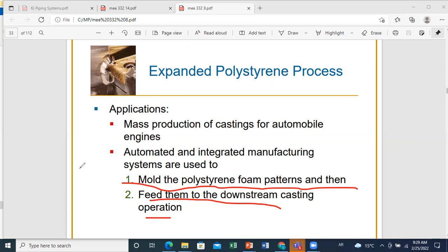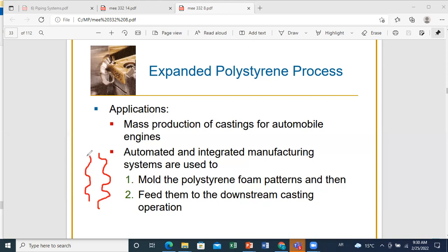In general, this system presents the advantage that you don't have to separate it into two parts, so you can directly create the whole system without having to divide your mold into two parts. Plus, you can control your curvature to a large extent, because with foam you can create any curvature you need. Foam is flexible; it allows you to make curvatures, to make complex geometries, etc.